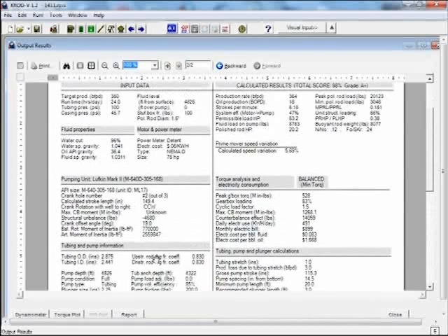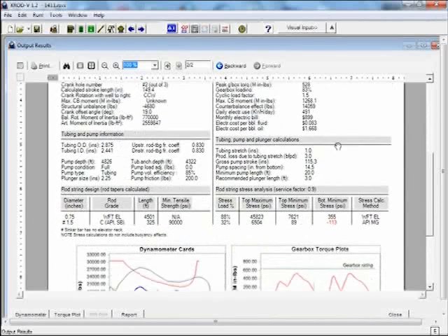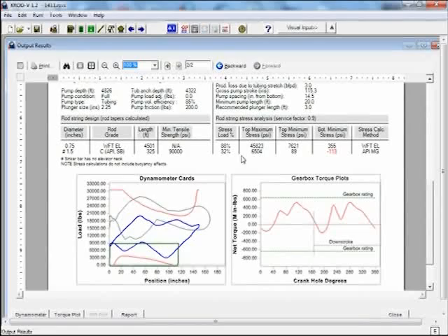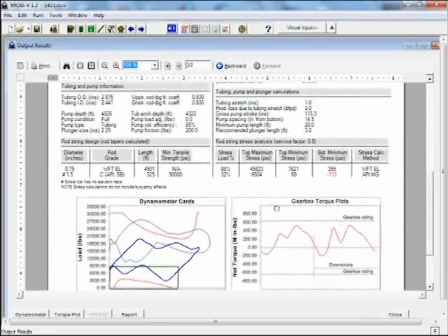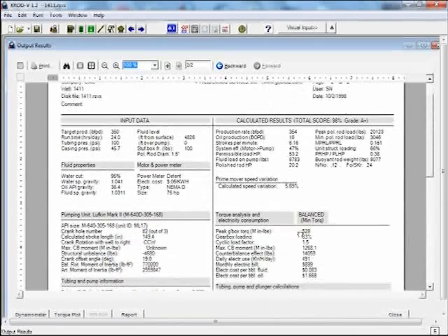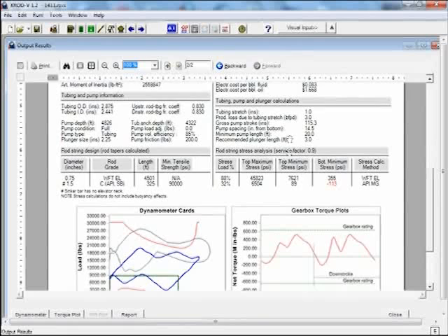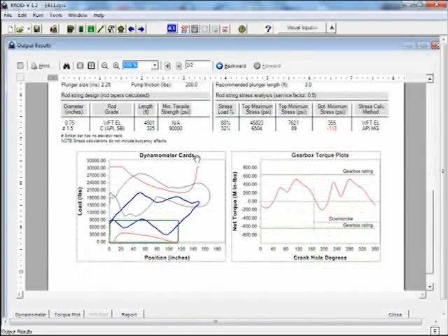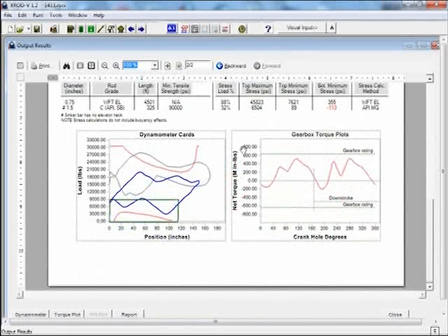with a 2 1/4 inch plunger, my efficiency will be very, very good. 47%. My structure loading will be 66%. My gearbox loading 83%. And I only need 3/4 inch rods all the way with 325 feet of single bars on the bottom to get the 350 barrels a day that I need at 24 hours a day.